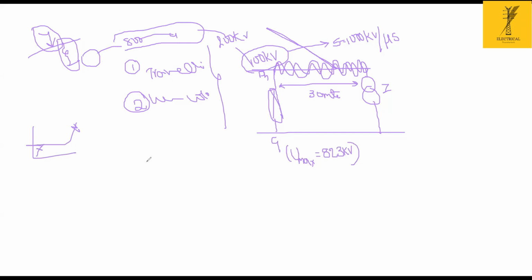And maybe due to the inductive voltage drop. We know that voltage U equals L into di by dt, right? Suppose the inductance offered by the line is 10 microhenries, and a lightning impulse current of 10 kiloamps per microsecond falls in the system. Then again it sees only 100 kV. For 100 kV, the lightning arrestor will generally not work. So these are the general ways of occurrence of lightning surges.